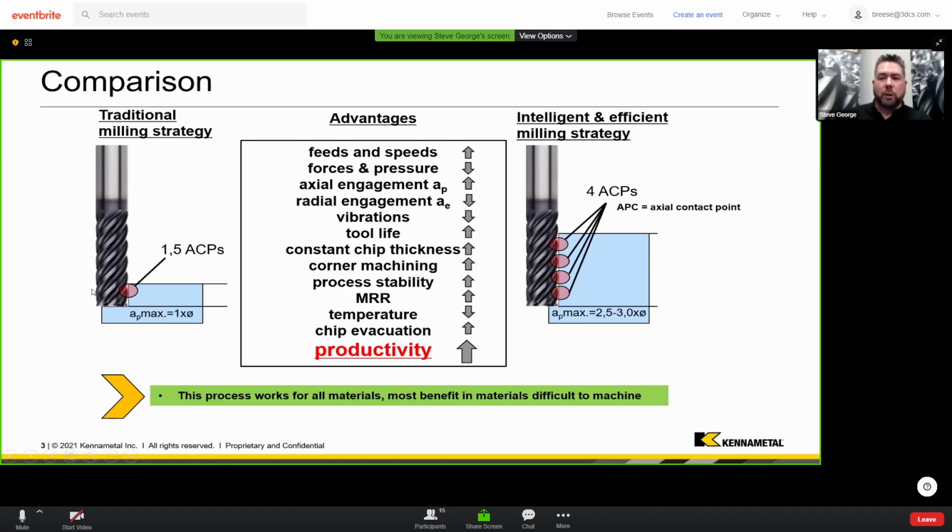So in traditional milling strategies, because of the short depth, even though I have a high radial depth of cut, I'm normally averaging about 1.5. So what does 1.5 mean? It means sometimes 2 edges are engaged. Most of the time it's 1. So you can expect more of the general deflection pattern. Here, it's a little bit more stable in a dynamic path because you're contacting more areas.